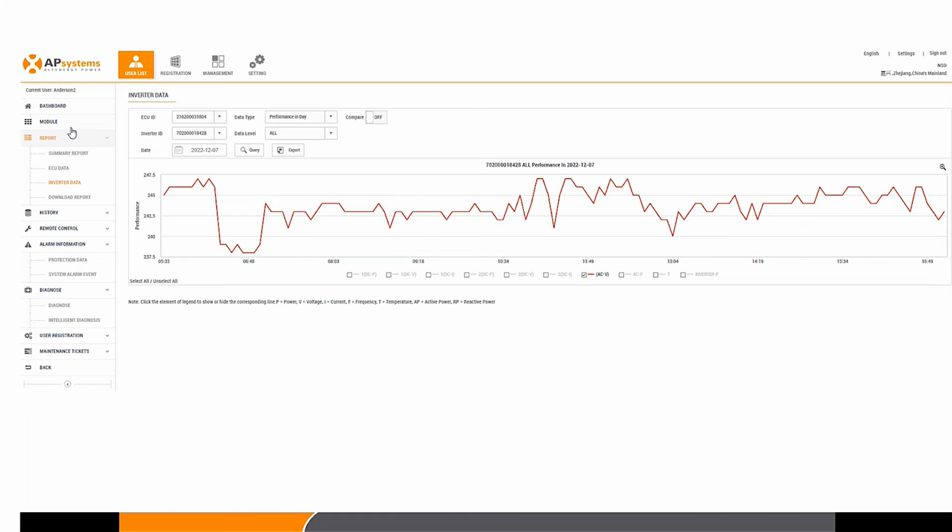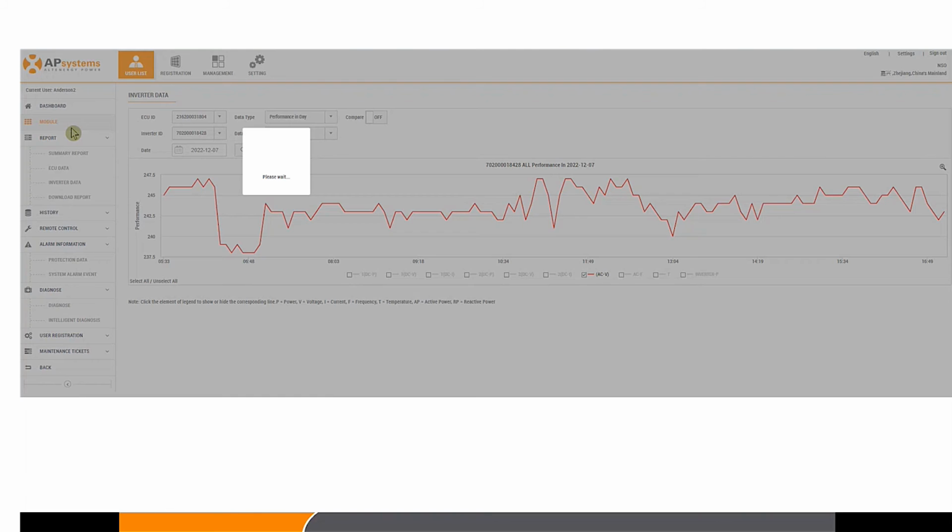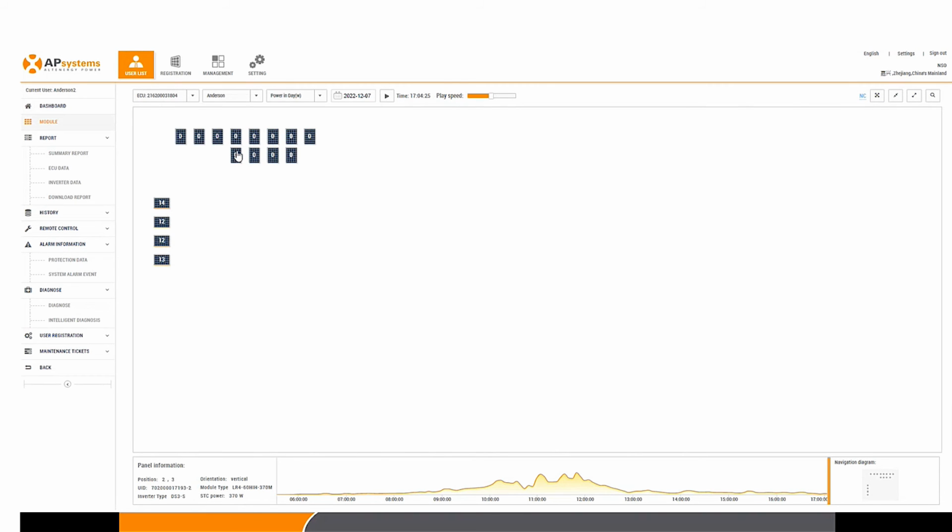So this is another example. If this installation were 2 breakers, it could also mean that the breaker's been tripped. So it could be both. It could be an AC disconnection or it could be the breaker has tripped. But I'm more probably leaning to the AC disconnection.